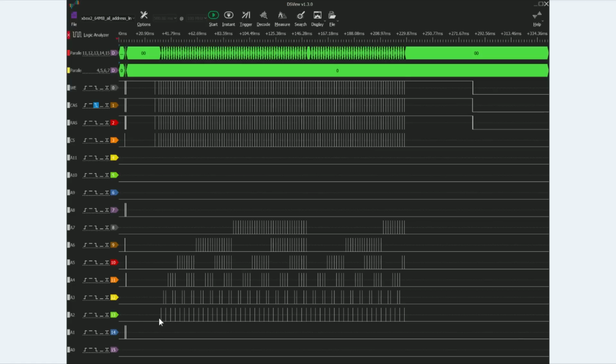We're seeing an increase in the address bus value as I'm going through memory. So we quickly see it ramp up from A2 to A3, all the way up to A7. So A7 goes high for a while, then that overflows. It doesn't overflow to A8, it overflows to another address bit. But yeah, the critical thing here is that A8 is not being used for addressing.